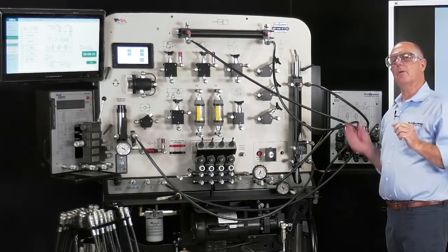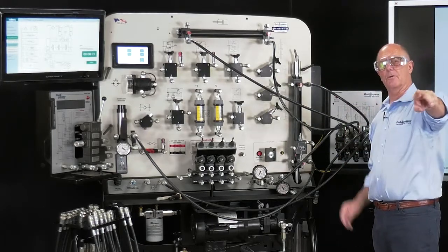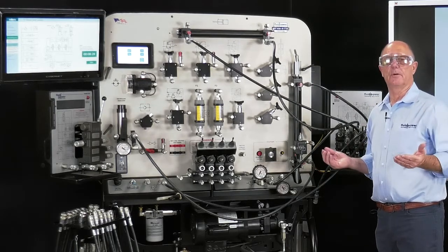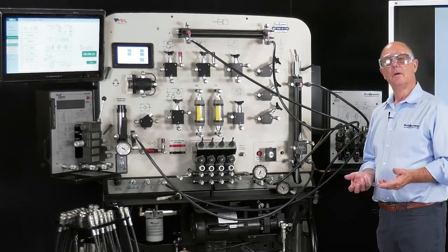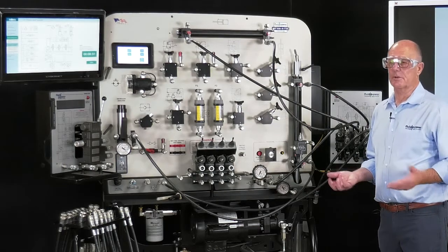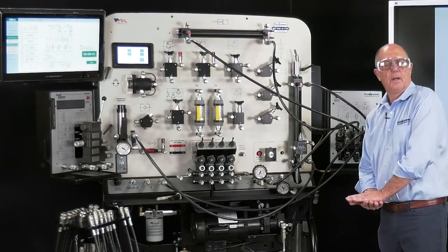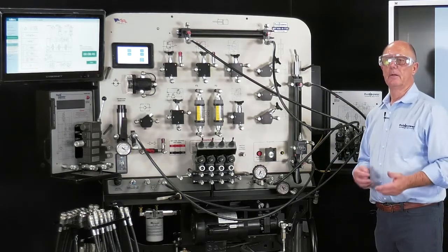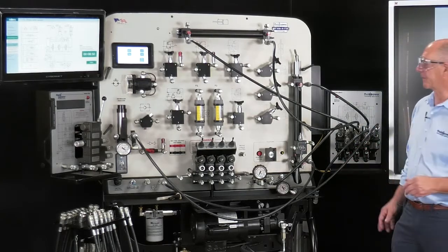The reason you want to take the line off the other side of the cylinder is because if you're going from the top of the cylinder to a closed valve, it's going to give you a false positive. So what you want to be able to do is see if it's leaking. Now, some people ask, how much oil does that thing hold? Because you're going to have to fill the cylinder. Well, it's not going to take much oil because the cylinder's already all the way down, so it's not going to have much volume. And if you need to fill it once or twice, you can do that, no problem. That's certainly feasible in that particular instance.